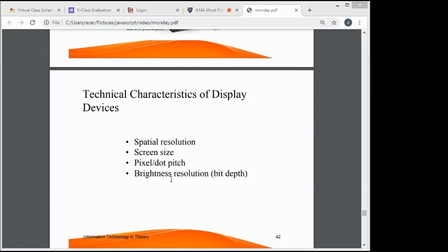For practical purposes, the clarity of the image is decided by the spatial resolution, not the number of pixels in an image. In effect, spatial resolution refers to the number of independent pixel values per unit length. Okay? So the spatial resolution of consumer displays ranges from 50 to 800 pixel lines per inch, with scanner optical resolution sometimes used to distinguish spatial resolution from the number of pixels per inch.